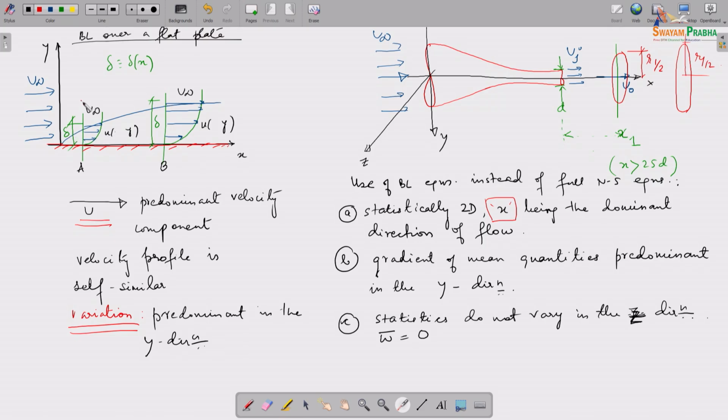Similarly, when I say spread of the jet, I am looking at these velocities, and as we saw in the last class, there is a v component of velocity in the y direction, and at one point it becomes 0 and then turns inwards, causing entrainment. So that is what we think is the edge. Here we demarcate this edge. The spread is not infinite, it reaches up to a height of r half. So this is how far the jet spreads.